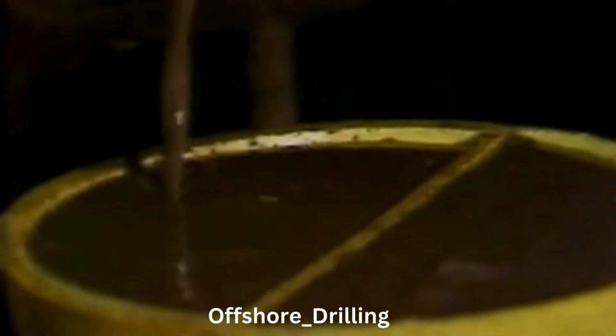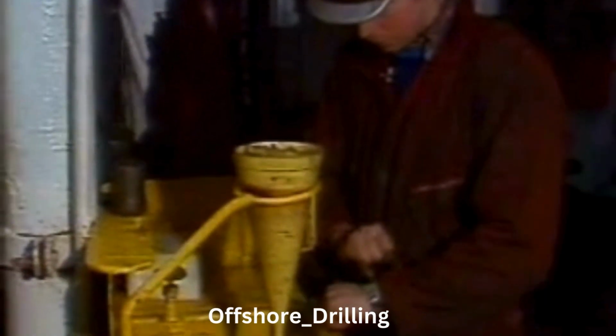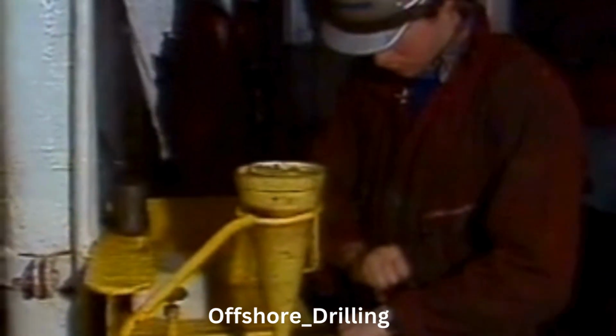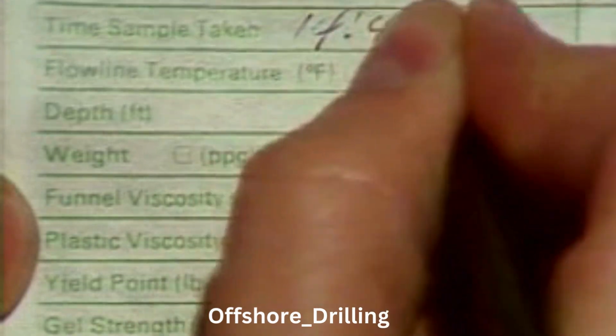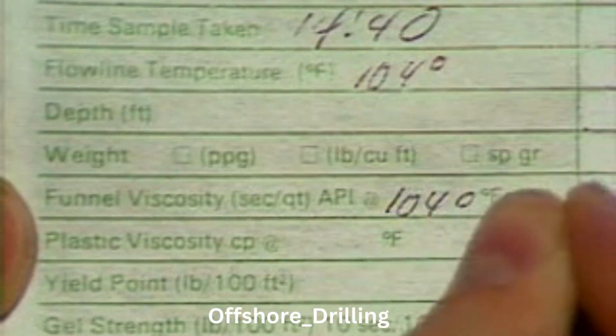Put your fingers over the hole and fill the funnel up to the screen. Make sure the mud is strained through the screen. Now, drain the mud into your cup or a beaker that has a 1-quart line. Time the flow from the time you first start it until it reaches the 1-quart line. Then enter the time into the logs. You'll need to log in the temperature of the mud too, since this will affect viscosity. Always be sure to clean your equipment up after using it.